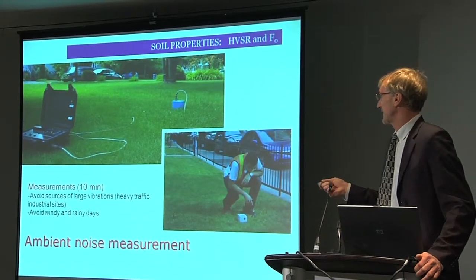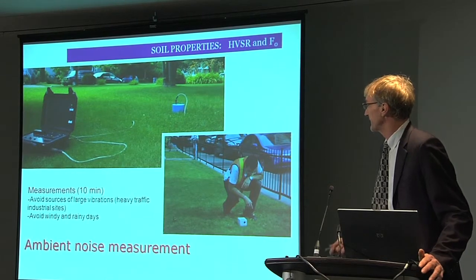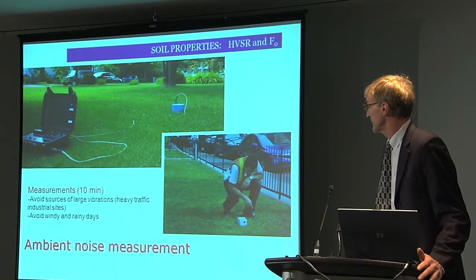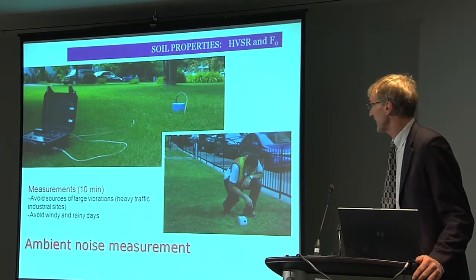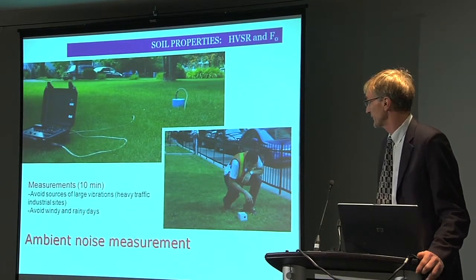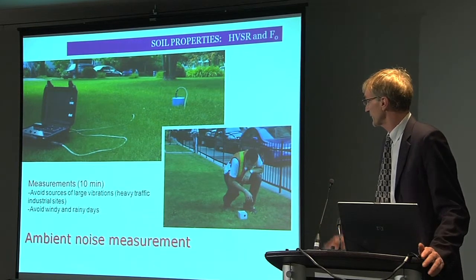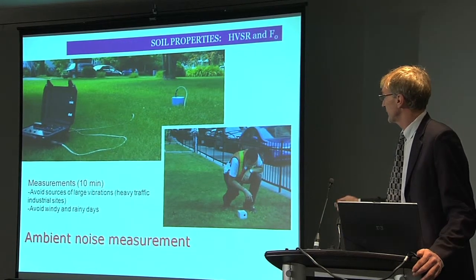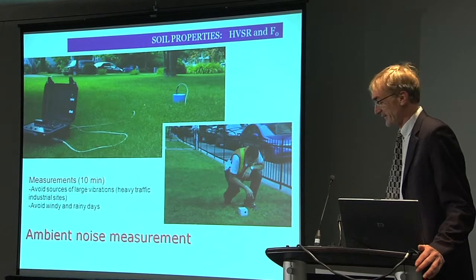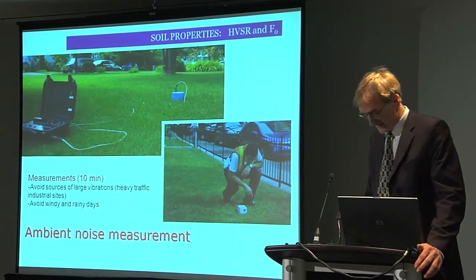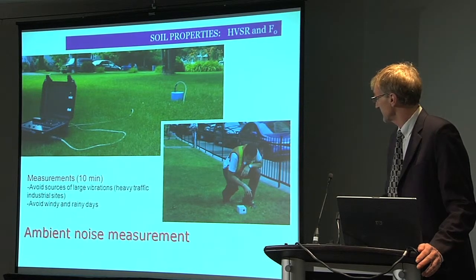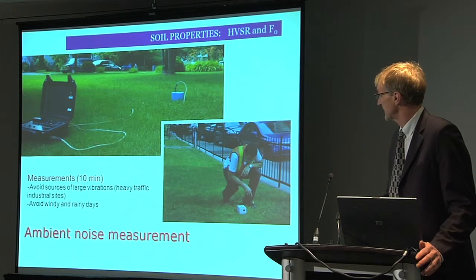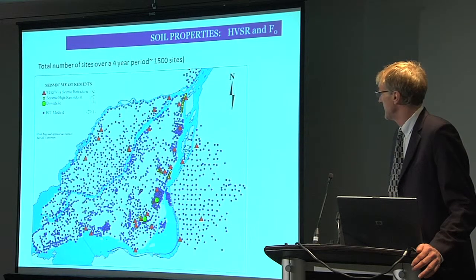The only thing you have to be careful about with this is that you have to avoid taking measurements when there are large vibrations. So you try to avoid going during heavy traffic or going close to industrial sites. You cannot work when it rains or if it's too windy. So a lot of the measurements done downtown were done by students very late at night. But otherwise, it's a very quick and cheap way of getting data on the ambient, on the natural frequency of a soil deposit.